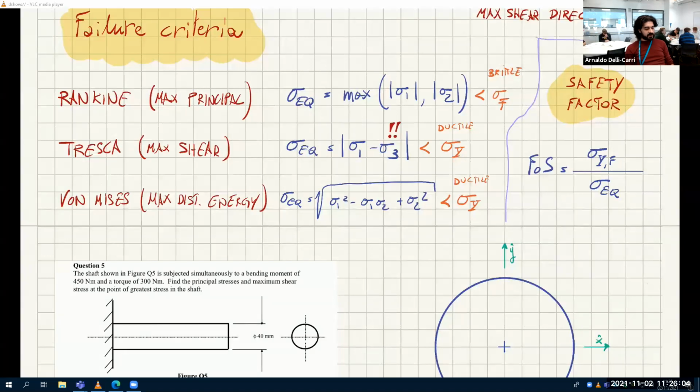Also, safety factor takes into account everything that you didn't account for in the design. So if you're not sure about some effects, or new materials that you use, then you want to increase this factor of safety. So you also put the factor of ignorance in your calculations.